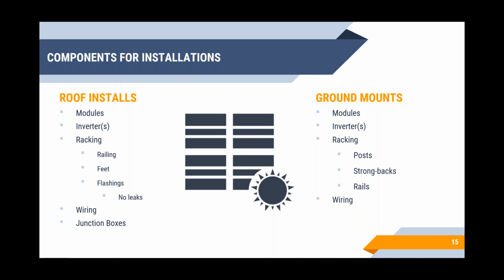On inverters, though, for ground mounts, we like to push the string inverter approach because, again, wiring is very easy on the ground, and you can bring everything back to a centralized string inverter that will hang on the post. From that inverter, the wiring will go into the building, most likely, but we'll be going on a fast track to the meter at that point with a disconnect. I'll get into that in just a moment.